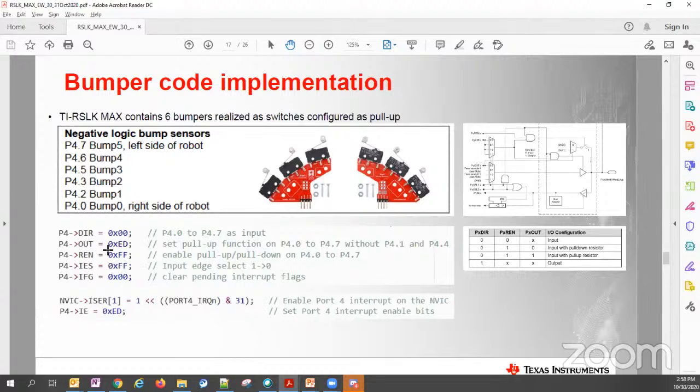So if I program this input pin to become a pull-up function, that means inside the chip, inside the processor, there is a little resistor which is mounted to 5 volt. And if I do that, as soon as I program these pins to become inputs, they will be high, but just slightly high.